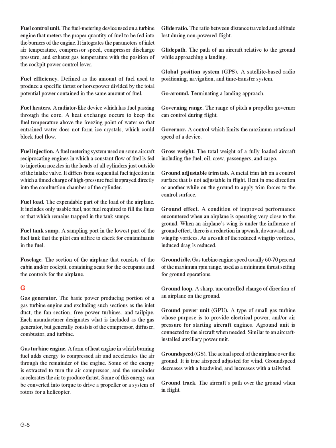Fuel heaters. A radiator-like device which has fuel passing through the core. A heat exchange occurs to keep the fuel temperature above the freezing point of water so that entrained water does not form ice crystals, which could block fuel flow. Fuel injection. A fuel metering system used on some aircraft reciprocating engines in which a constant flow of fuel is fed to injection nozzles in the heads of all cylinders just outside of the intake valve.